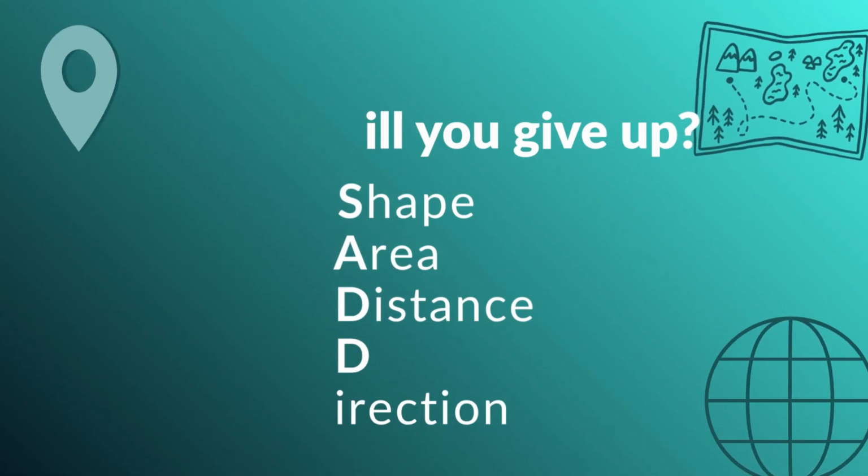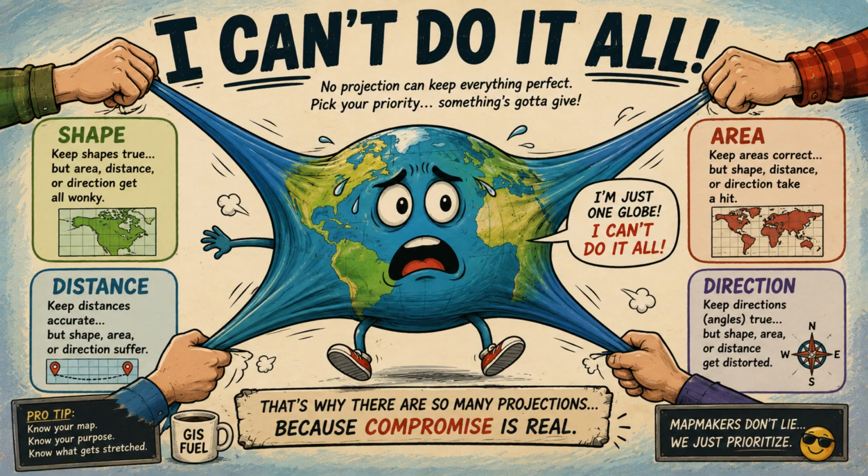To project the 3D data, cartographers use what are called developable surfaces. Basically, they conceptually wrap a geometric shape around the globe. And the three main surfaces you must know are planes, cylinders, and cones. Got it. How that surface intersects with the globe dictates exactly where the distortion occurs. Okay, break that down for us.